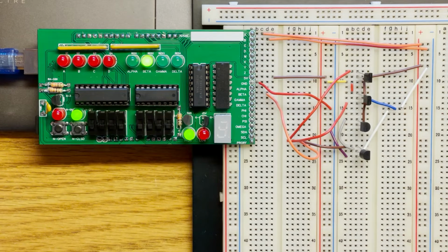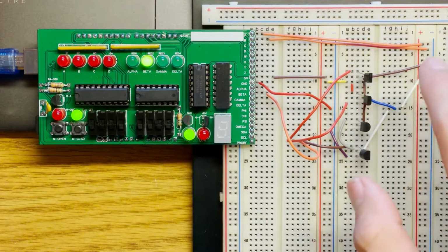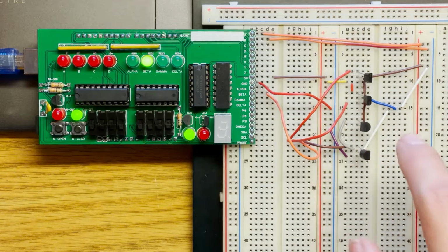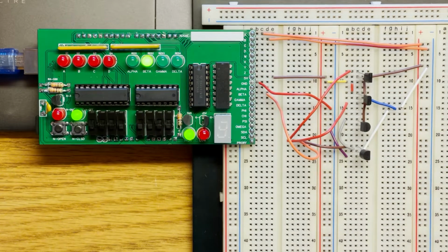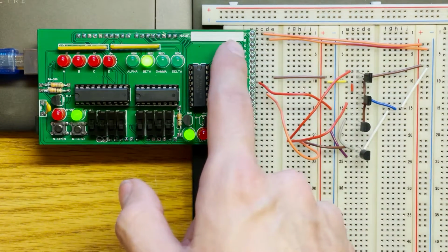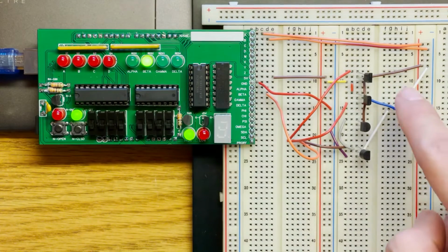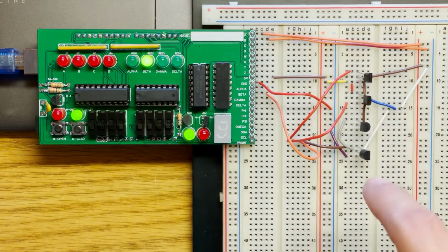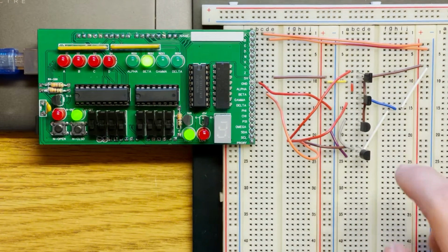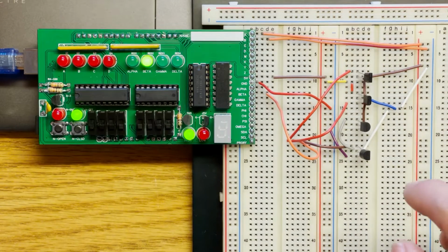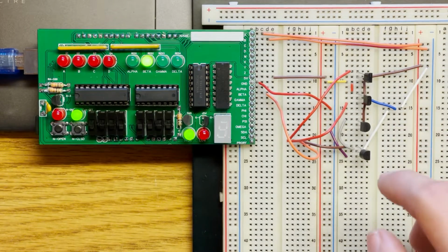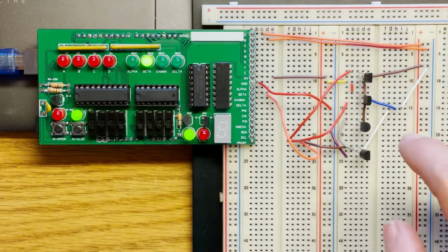This is lab 1. The purpose of this lab is to implement logic functions using only CMOS transistors. So I have my NMOS right up here and my PMOS down here. And we're simply taking two inputs, A and B, and putting them through these two different types of transistors. These two types of transistors make up what's called a pull-up and pull-down network.